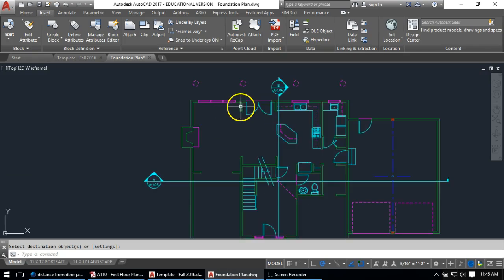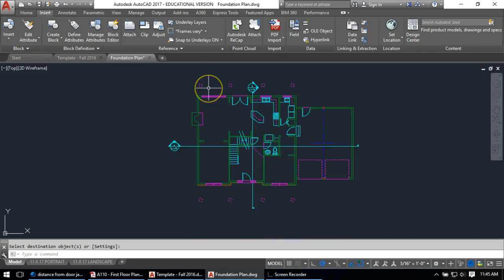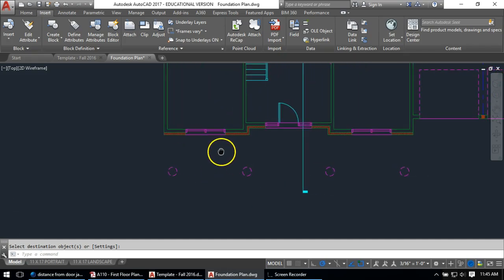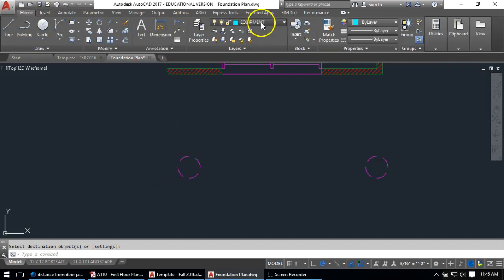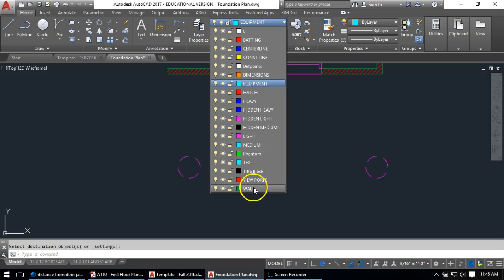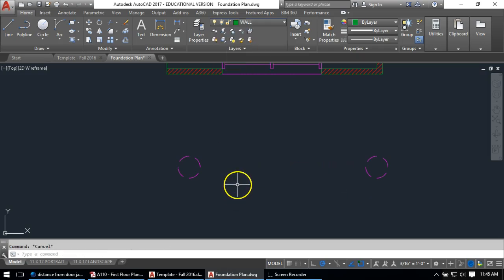I've got these decks to do on the outside as well. So this one's shortened because we had to shorten it to get it on the page, right? So that's why we did that. And this one needs to be drawn at full size. And you see these little X's where the 6x6, that's what the notes say, 6x6 posts are coming up. Those are going to be centered right on this point. So I can go to my home layer. I can go to my walls layer, and I can draw a polyline that's 5.5. That's what a 6x6 is, a 5.5 by 5.5.